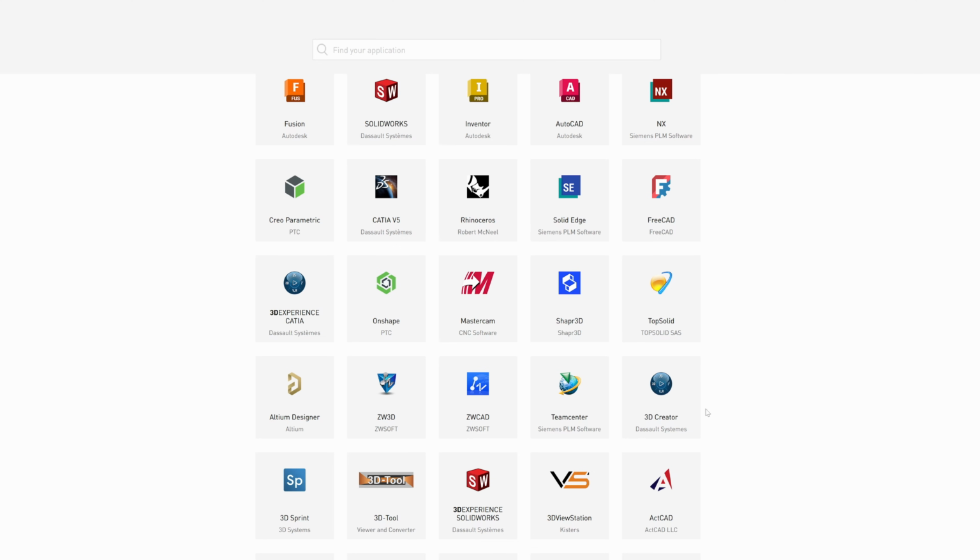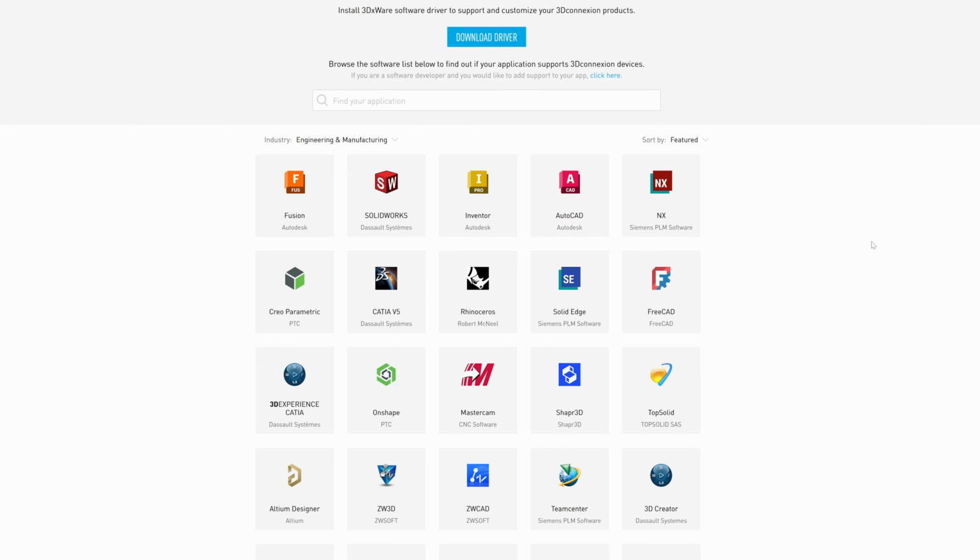Okay, this is the 3D connection website. The CAD software that supports intersection curve will be Inventor, SolidWorks, Solid Edge, Rhinoceros, CATIA. I'm not sure about Creo. FreeCAD cannot do the 3D line, so it's not supported. Fusion does not directly support intersection curve. You need to intersect two surfaces. And same for AutoCAD. AutoCAD also cannot do the curve intersection. For Autodesk Inventor, this function has been around for years, more than 15 years.